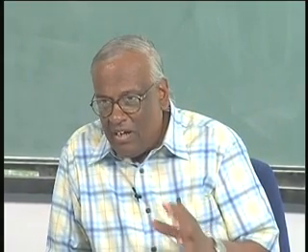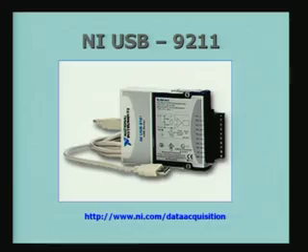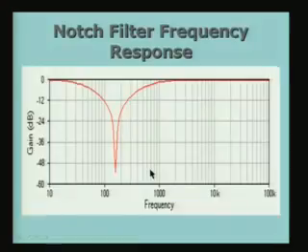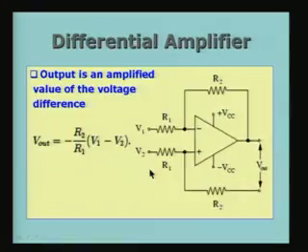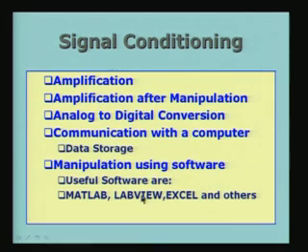All the items which I mentioned are already built into this 9211. So, you do not have to connect anything specifically to that, it is already there, and the software will take care of most of the things. And as I said earlier, the software which comes with National Instruments is LabVIEW. So, if you look at the LabVIEW software, with LabVIEW you can design the appearance of the instrument.